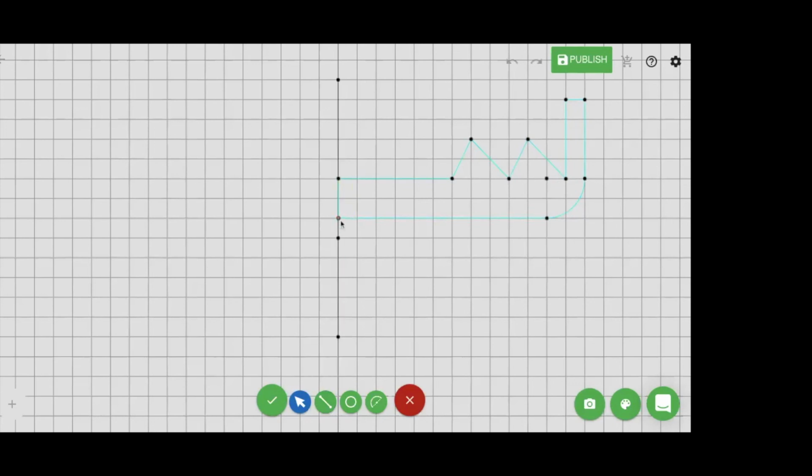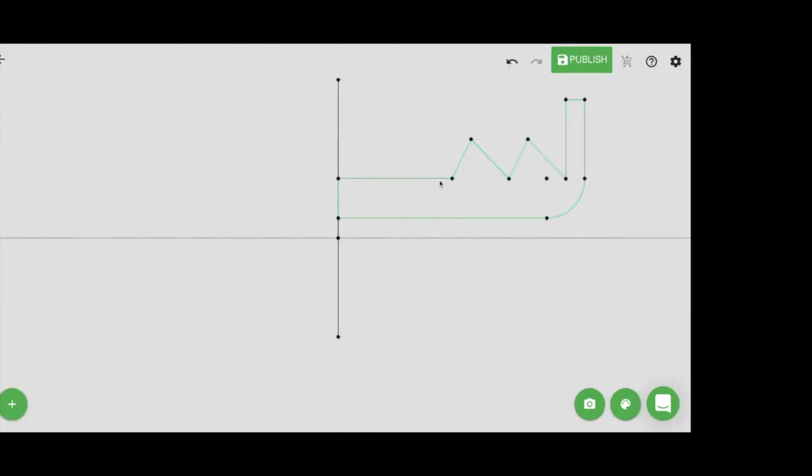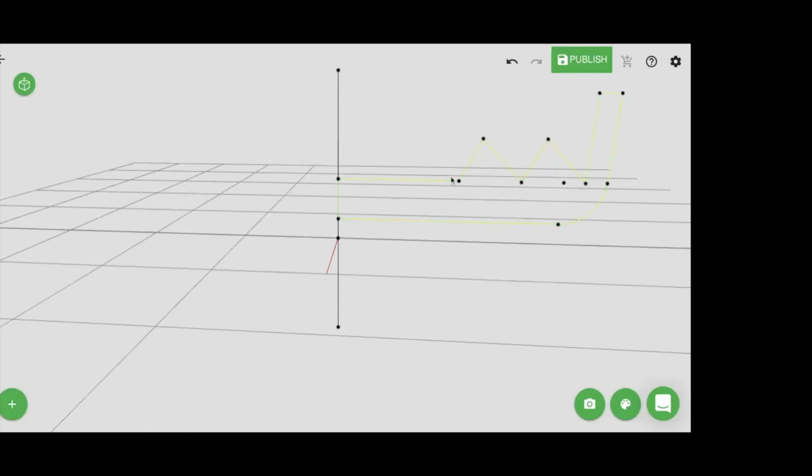All right, so I want this to sit on this construction line. So I'm going to hold the dot, click the line, press this button so its point goes on the line, and now it's stuck there and everything's good to go. So I'm going to close this, and I could just click this and extrude it out, but then that'd become this weird bracket shape again. But in this case, I'm going to hold control and also select that center line.